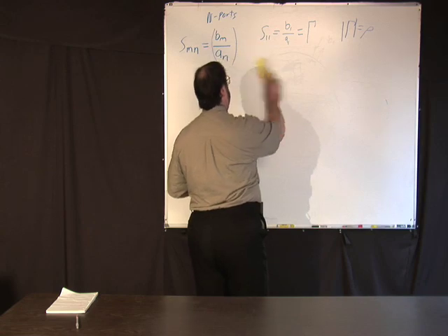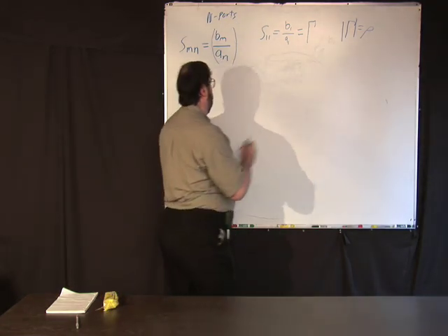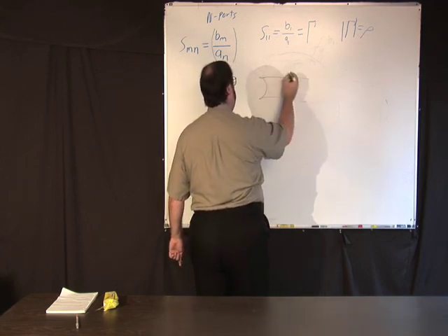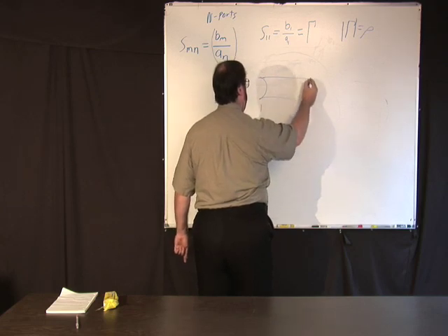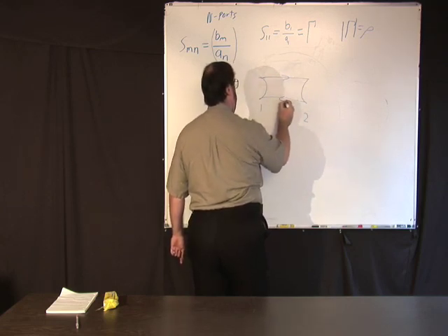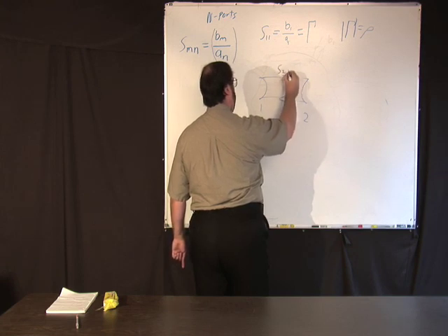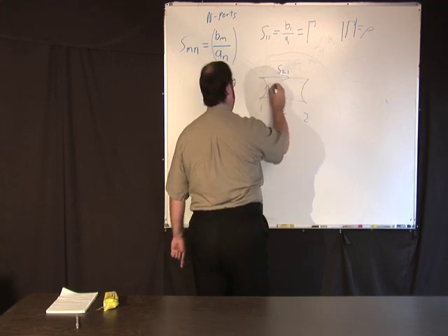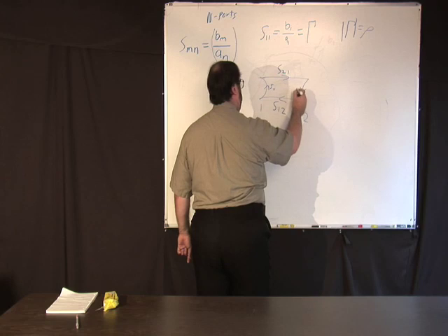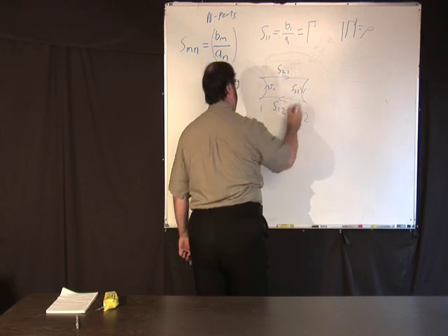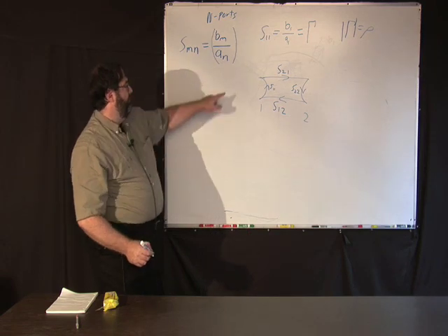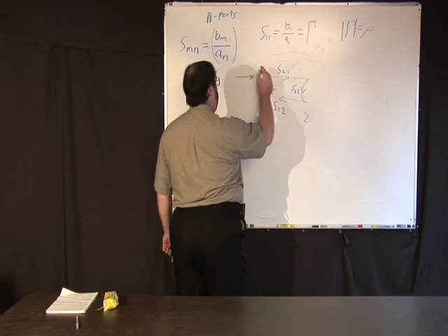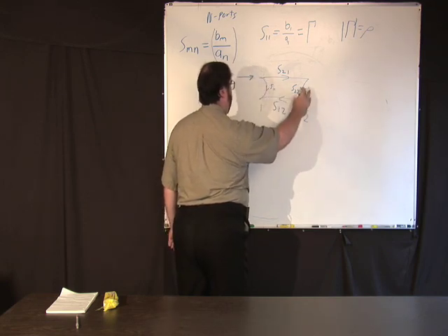We just did a one-port device. This is probably the most common thing you'll see: you draw this with lines and arrows usually. So this is port 1, this is port 2, and this is called a scattering diagram, where this arrow is S12, this is S21, this is S11, and this is S22. Four-port device. So if you had an A1 going, or sorry, yeah, an A1, oh, I got these arrows backwards.